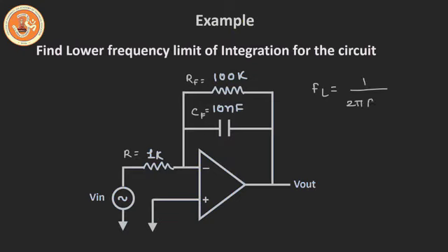For proper integration, the input signal frequency should be larger than this cutoff frequency FL, and it should be at least 10 times this cutoff frequency FL. So, in this way, based on your input signal range, you can design your integrator. Now, let's see the second example.